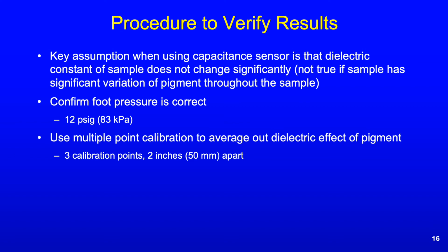The mechanical profiler uses a mechanical system to counterbalance the weight inside, and it's a fixed pressure, and you specify that according to the test method that you can use, and that's how it arrives from the factory. With the capacitance gauge profiler, that caliper's foot pressure is adjusted with air pressure, compressed air. So you can adjust it, and I just made sure it was appropriate.